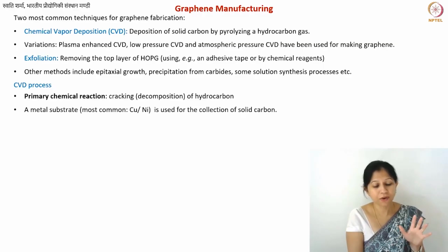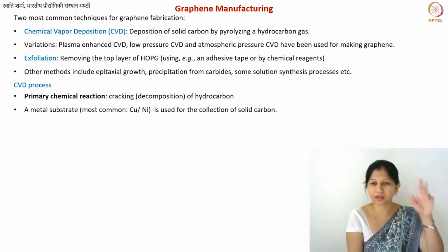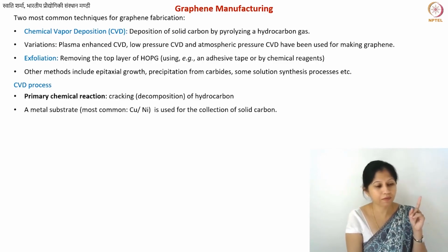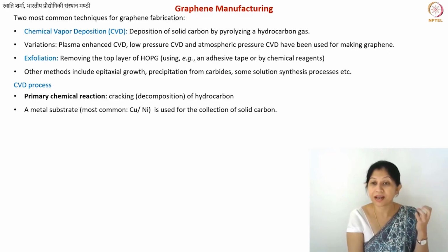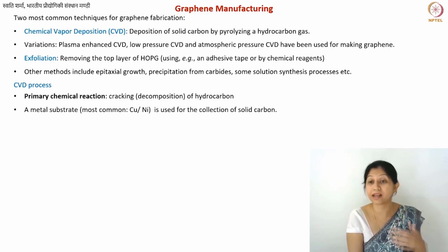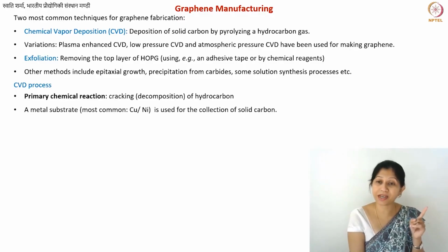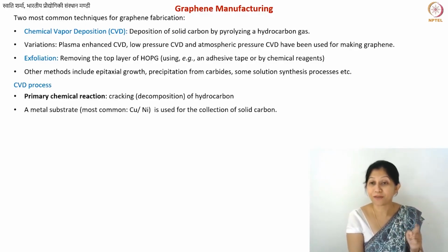Okay. If you remember, we were also talking about pore filling. This is a little bit of a different topic, but then we'll come back to the same point. When we were making needle coke structures, for example, needle coke to graphite, we did the first carbonization step, and then we had a lot of pores in our structure. We filled resin or pitch inside those pores, and then we carbonized it again and then again and again to fill these pores. That pore filling can also be done using pyrolysis of hydrocarbon.